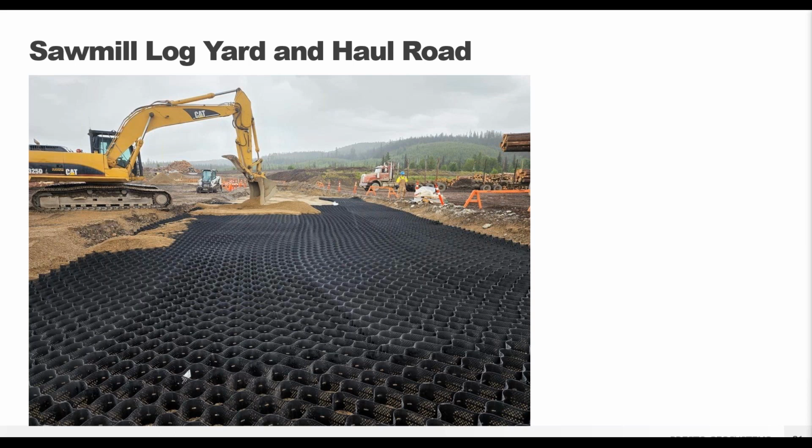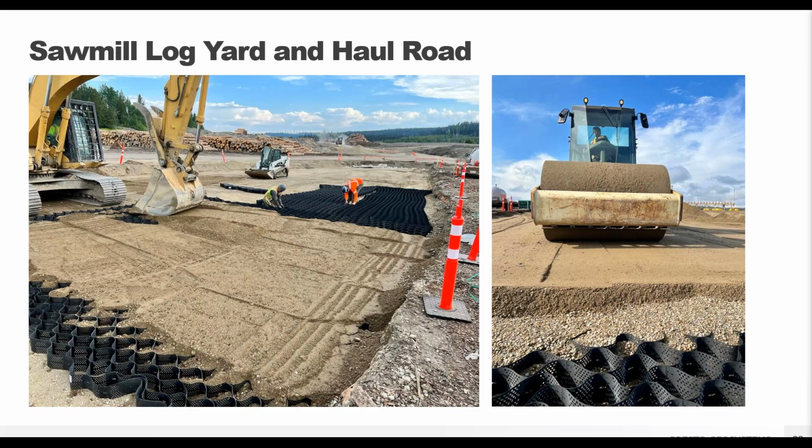So when you know that you're going to have heavy daily traffic, in this case, fully loaded trucks bringing logs into the sawmill, this is a good way to make sure that you don't have to constantly be going back and replacing and regrading the access road. The GeoWeb system is going to be a permanent, long-term solution.